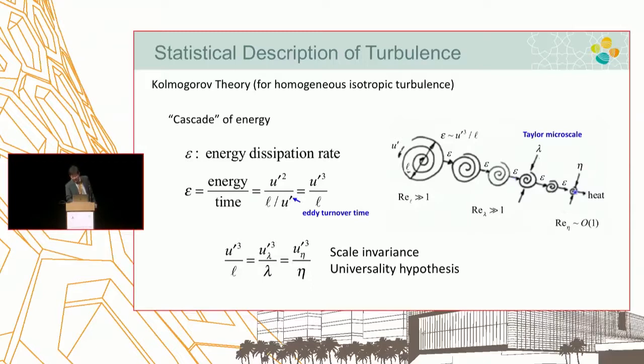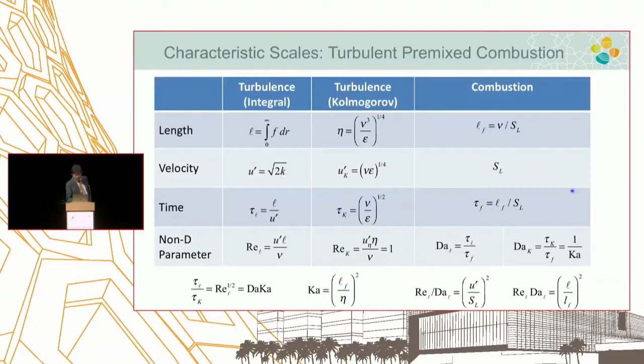And then where does it end? That's the next question. It ends as the eddy size shrinks into smaller and smaller, and molecular dissipation and diffusion start to play a role. So that scale can be estimated based on the molecular diffusion and energy dissipation. It's all dimensional analysis, chapter 7 of the fluid mechanics book, the pi theorem, and you can easily get that.